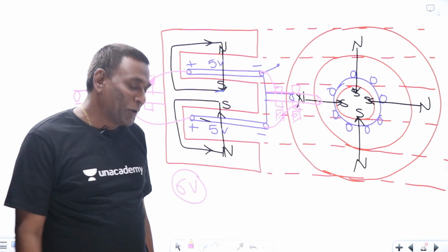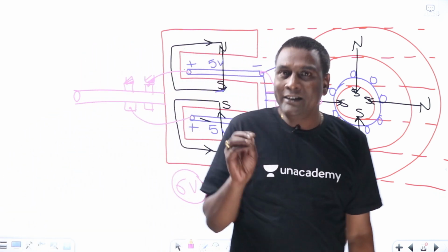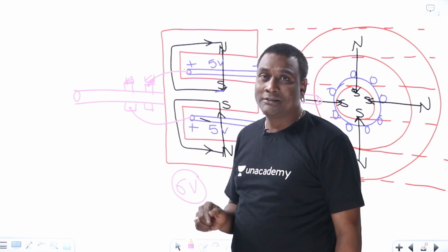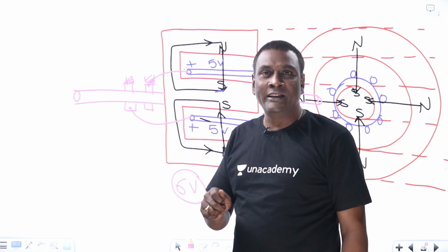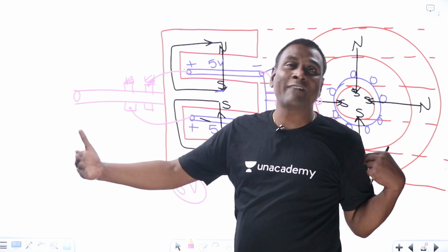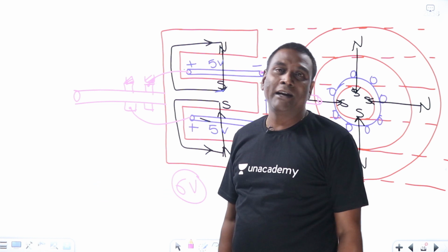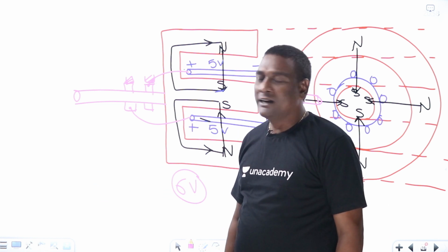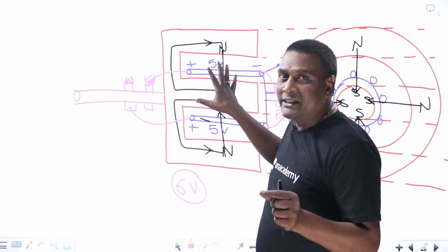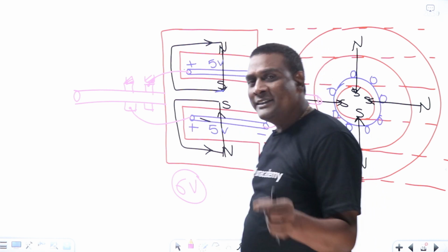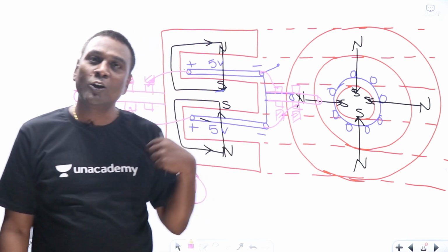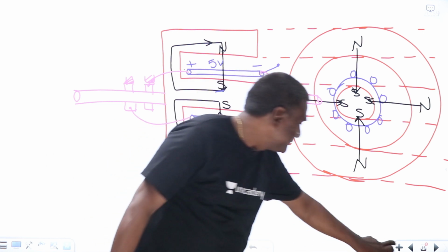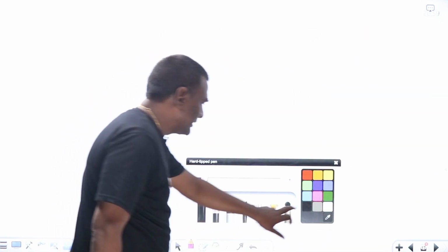How much will be the length of the shaft? Kilometers wise, right? So the point here is very simple. A homopolar structure is available to do, but from the cost point of view, the length of the shaft will be in meters or kilometers, which will increase the cost of the machine. Getting my point, right? So the disadvantage with homopolar is that a significant amount of voltage cannot be taken. So commercially it is not used.